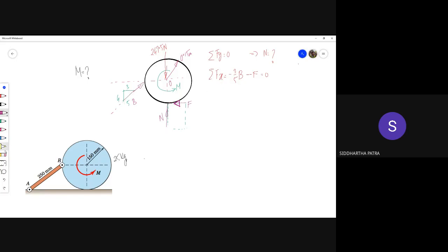Okay, then I don't have to use this negative sign right here. Now that is not mandatory. I can go ahead with the negative sign, and ultimately I'll get a negative value. But when it comes to friction, not showing the correct direction can be a problem. So for friction, you need to figure out in which direction we are about to have relative motion, and in that case, in which direction should the friction force act, and the direction of the friction force should be correct.